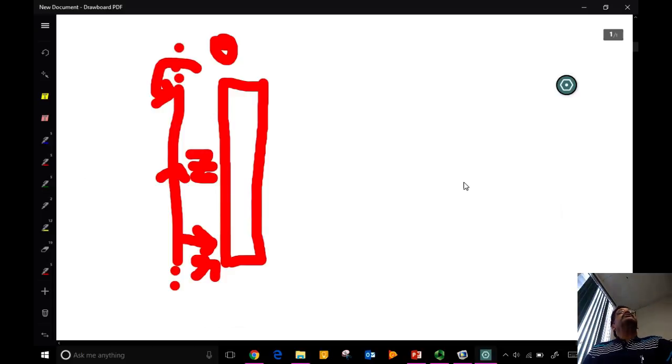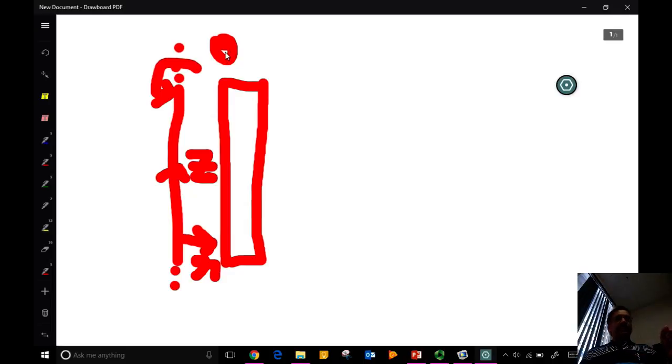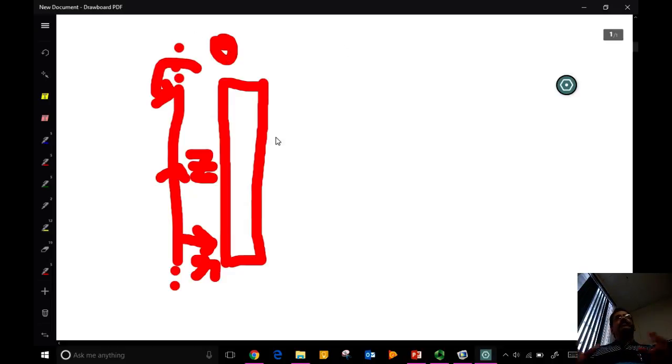But it is also used in a viscometer. Why is it useful to measure viscosity? Because if you take the inner cylinder and rotate it by mounting it on a motor at a constant speed, that creates a flow field between the inner cylinder and the outer cylinder. Then mount the outer cylinder on a torsion bar.